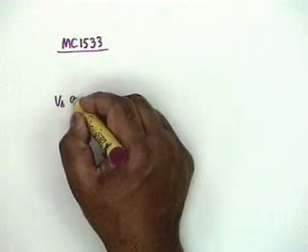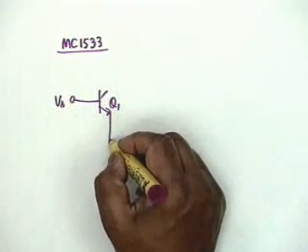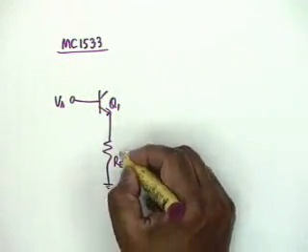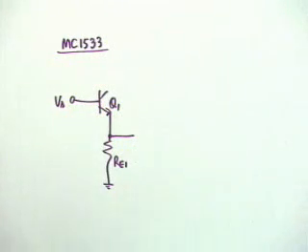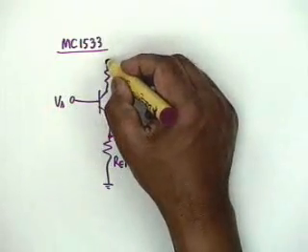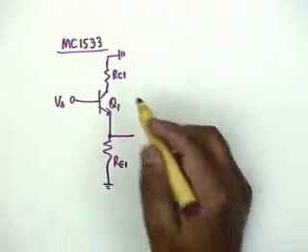You have a source Vs which goes to a transistor Q1. Q1 has an RE1, and the feedback is applied to RE1, so the comparison shall be series or shunt? Series. Okay, this we are already familiar with. Then this has an RC1, and let us say it is grounded. That is, it goes to the power supply. I am drawing only the AC equivalent circuit.